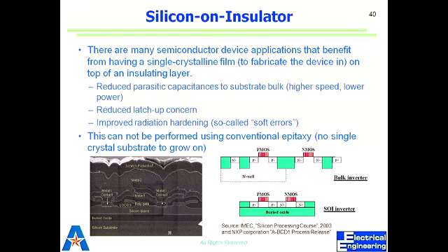That also gives you silicon on top, silicon at the bottom, and silicon dioxide in between. What happens to the crystal structure when you do that? When you are bonding them, they essentially merge into each other. The boundary is still crystalline. There would be defects, of course, but now you have a playing field on both sides.